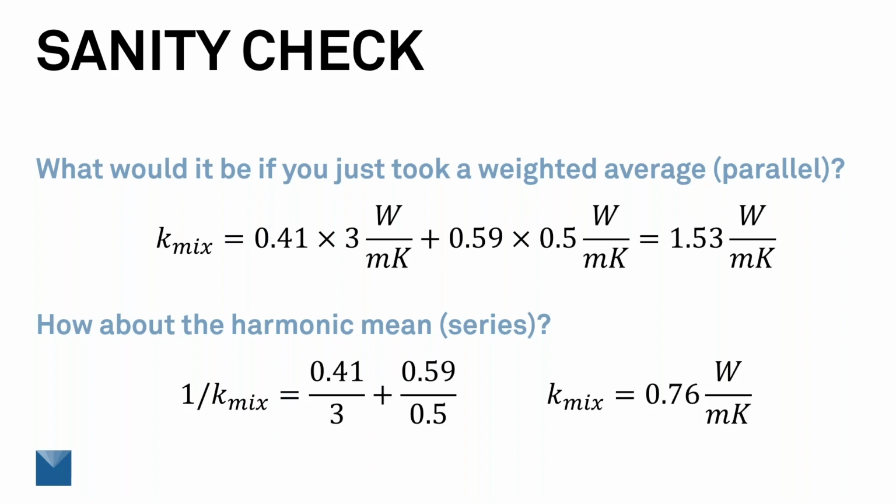Now, is there any advantage to having a soil profile that's dominated by rock, the way our calculation shows here? Well, of course there is. When we bury a cable and it heats up, the heat that it gives off will drive water away from the cable.